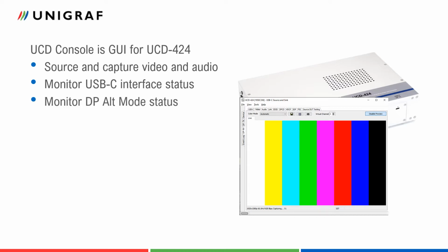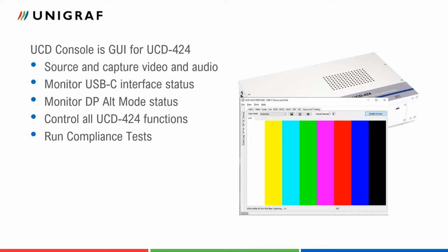All UCD-424 parameters related to the USB-C interface or DisplayPort alt mode are available for the user through UCD Console dialogues. UCD Console also includes the dialog for running link layer and HDCP compliance tests. The test functionalities will be enabled with a separate license.